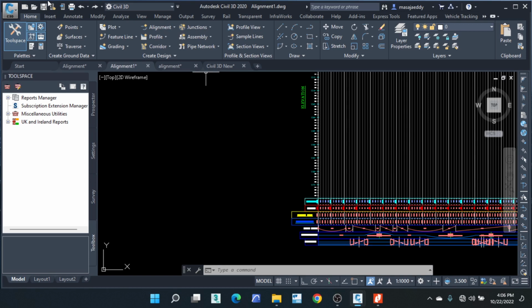This is the swamp. Make sure for the swamp we ignore the minimum, so it remains like the ground. We shall just bank the road on one side. And if it is less than 0.5, it's fine. We shall just bank it on one side, and the water can still flow off the road. And not something like this.